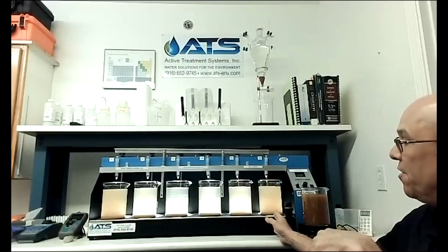What I have done, and why this is remaining dirty, is I have applied an excessive amount of a cationic polymer. Before, when we had suspended solids like we have in our control sample, these negative repelling charges are keeping each other from wanting to come together and settle. What's happening here is I've added enough cationic polymer, I've overdosed, and I've changed the solution in the water from an anionic repellent to a cationic repellent. So this water at 550 NTU would not be a good dose to start with.